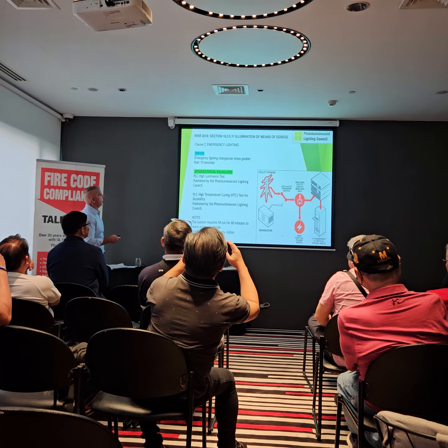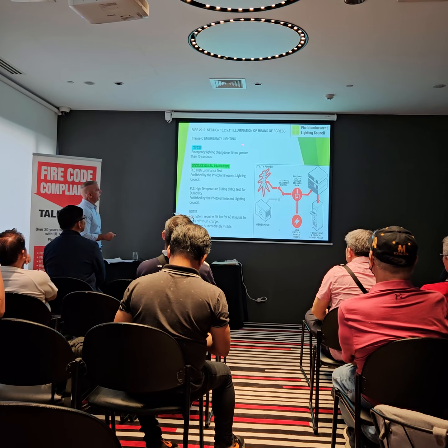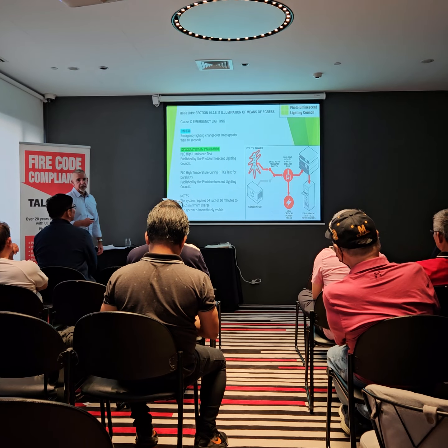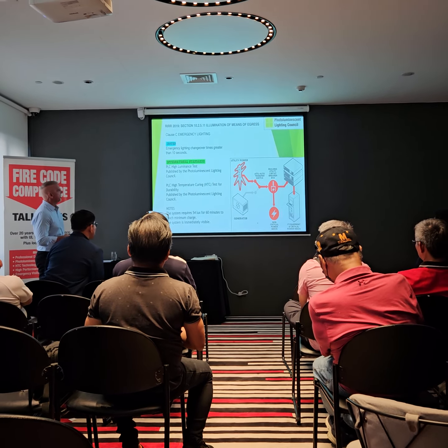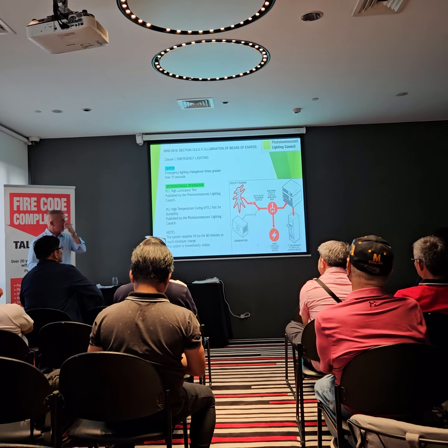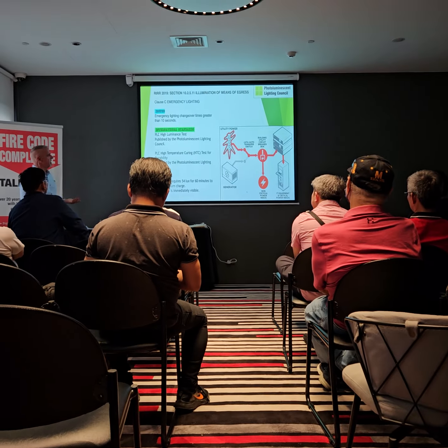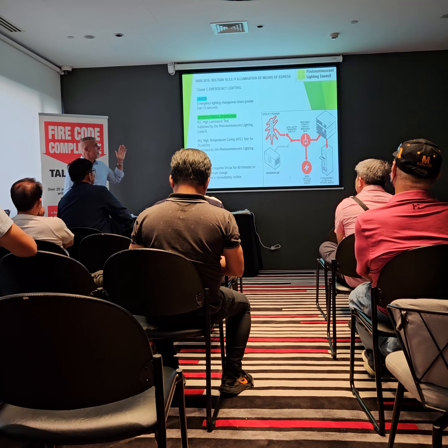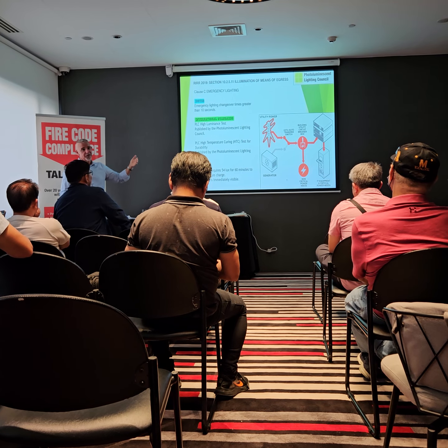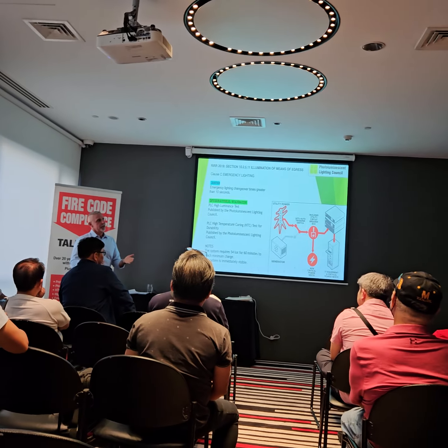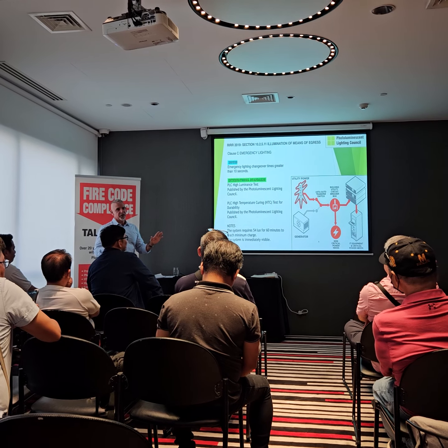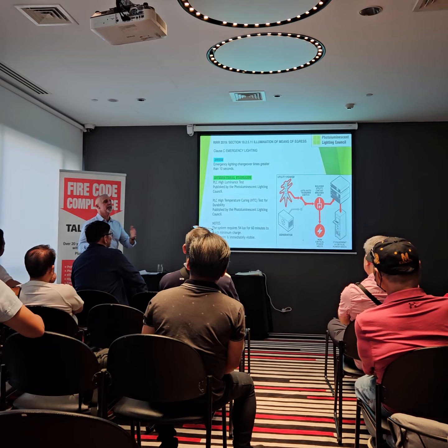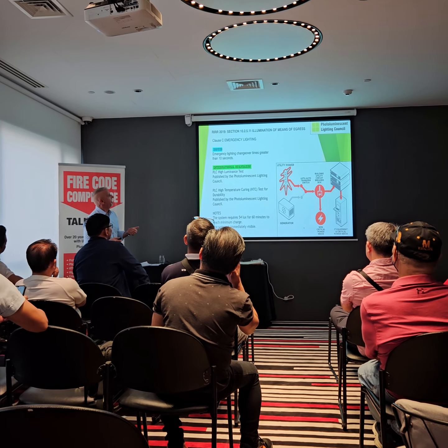Clause C refers to the changeover time of the emergency lighting system. 10 seconds is pretty common around the world for minimum startup times for generators. It isn't always possible. The thing with photoluminescence is that it's instant. So if you have longer startup or changeover times, you don't want it going totally black for 20 or 30 seconds, because that's long enough for people to start panicking. And once they panic, they don't unpanic very well.